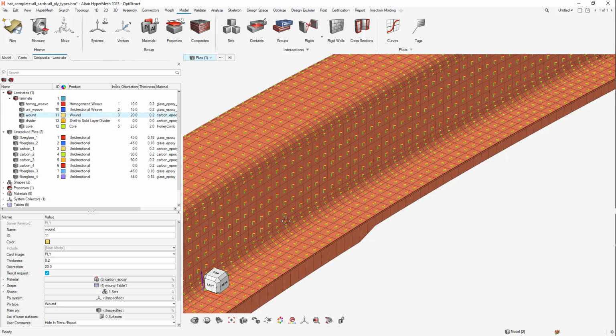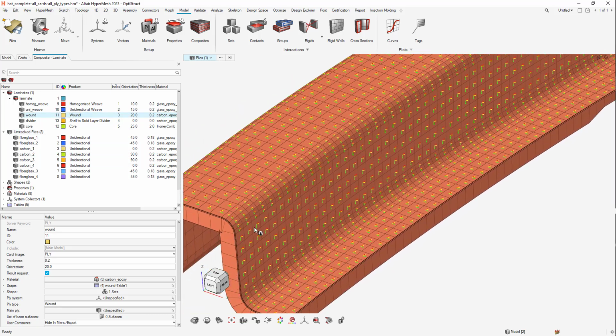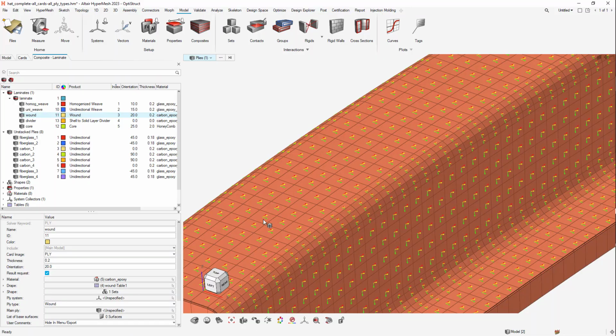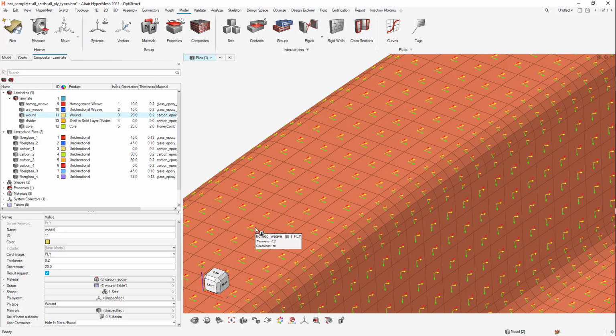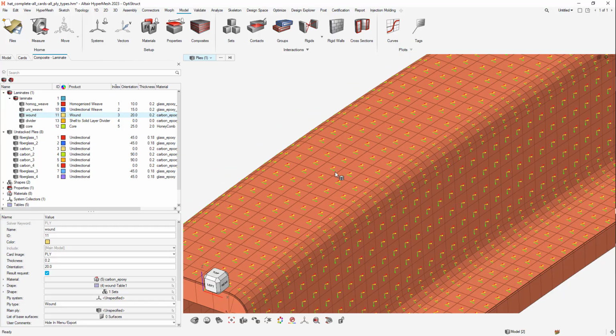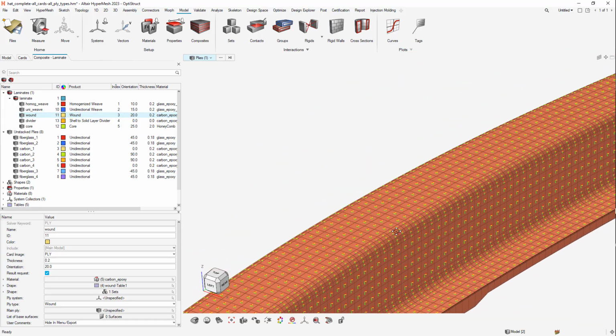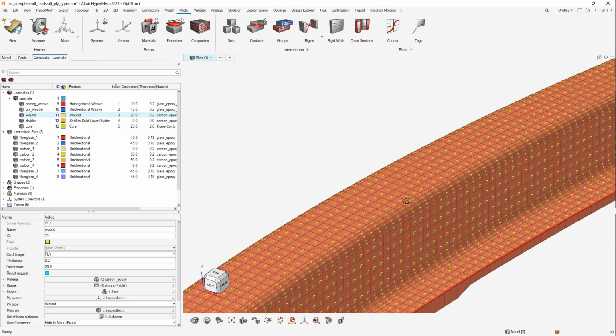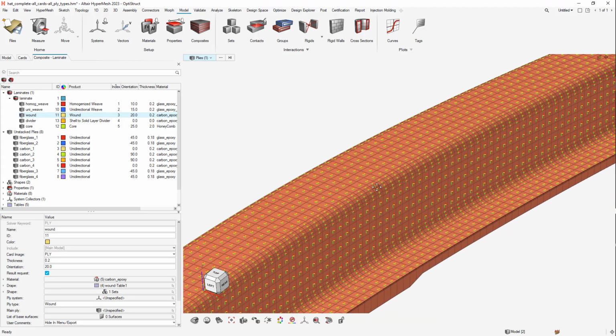We got the wound ply, and the wound ply itself has one layer here, but it can have n different slices, with then each the corresponding yellow arrows here for the orientation. As you can imagine, this case here is not coming from a filament wound model, so this is more or less just to illustrate that, okay, you have to have a drape table, and then values are going to be shown correspondingly.